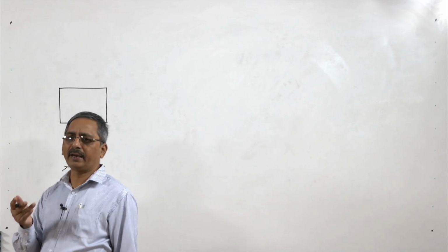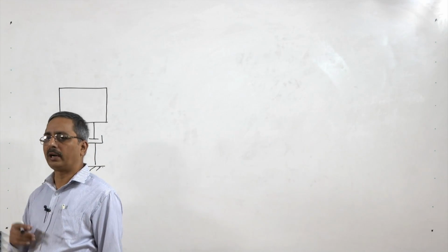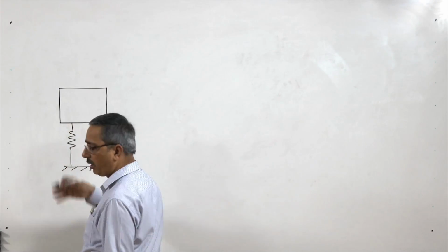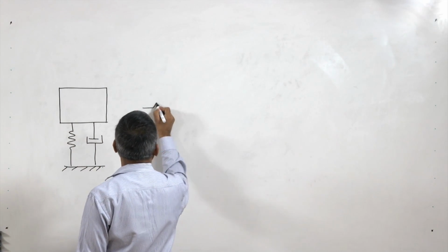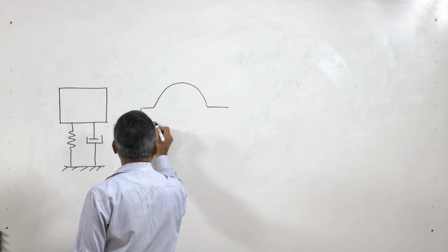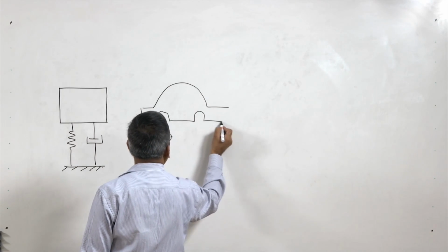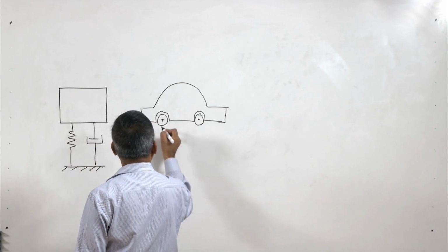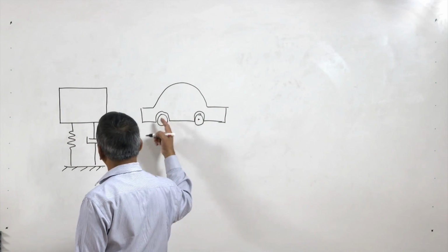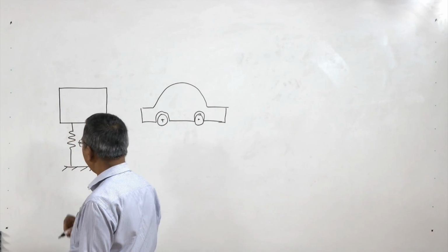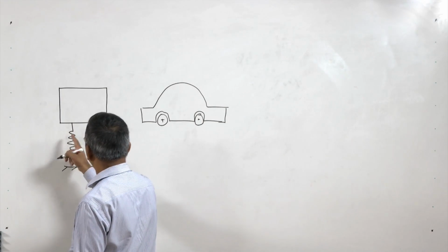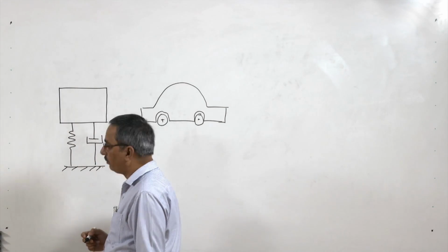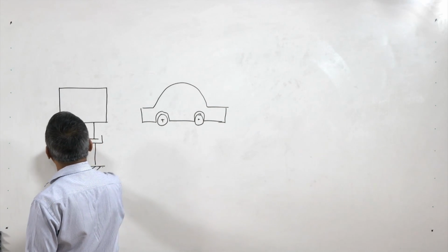For example, in my earlier lectures I talked about modeling of a water tank, and we could always make this type of model for a system. Say I have a simple car and I want to mathematically model it. The equivalent suspension system I can represent using a spring and damper, and the mass of the car by a lumped mass.